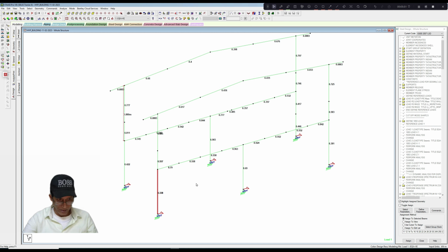reduce the size of the flange, but for a column it is better not to reduce the flange width to less than 150 mm. And it is always better to have a web depth of uniform depth at top and bottom, so that the axial load that is being transferred to the column below is not eccentric.